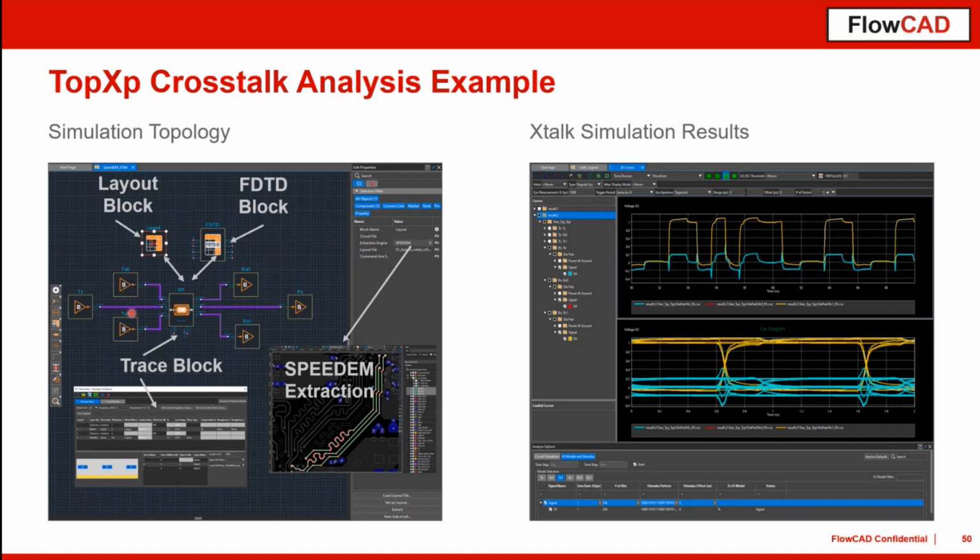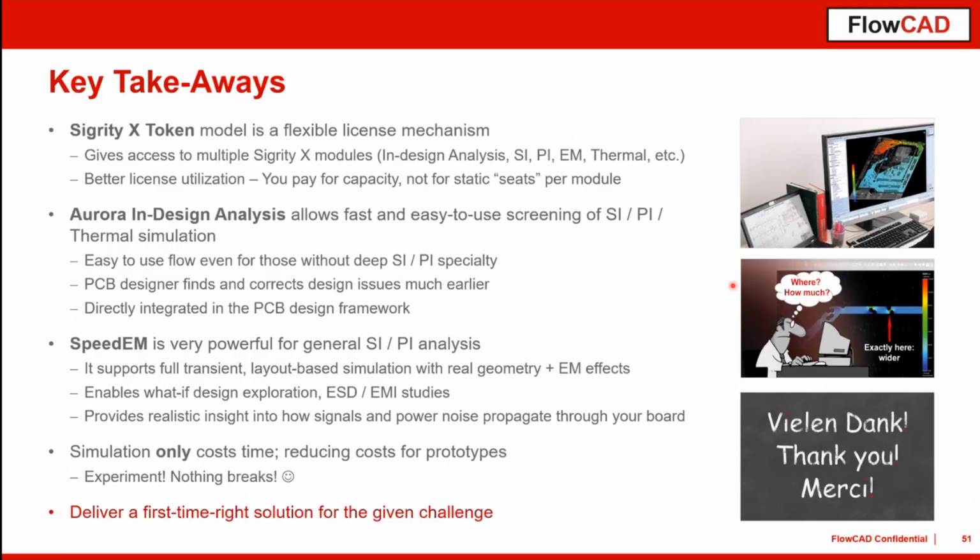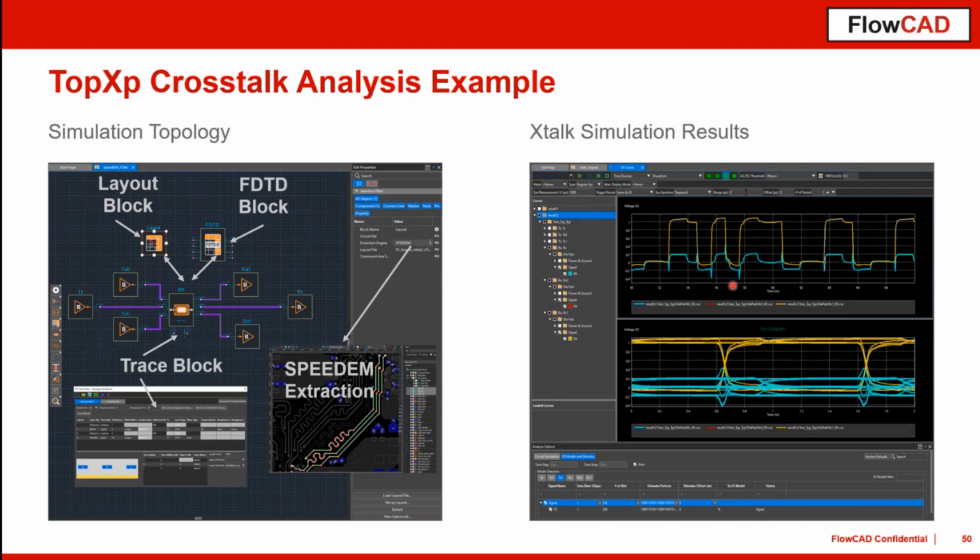So it's a very nice way to connect different blocks, different objects, to create a complete channel analysis, for example. Once this is done, you can also configure your driver and receiver sides in the Topology Explorer: stimulus pattern, number of bits to be transmitted, data rate, and so on. And then finally you get those transient analyses. From my side, it's a very powerful tool that can be used at very different stages of your design process.